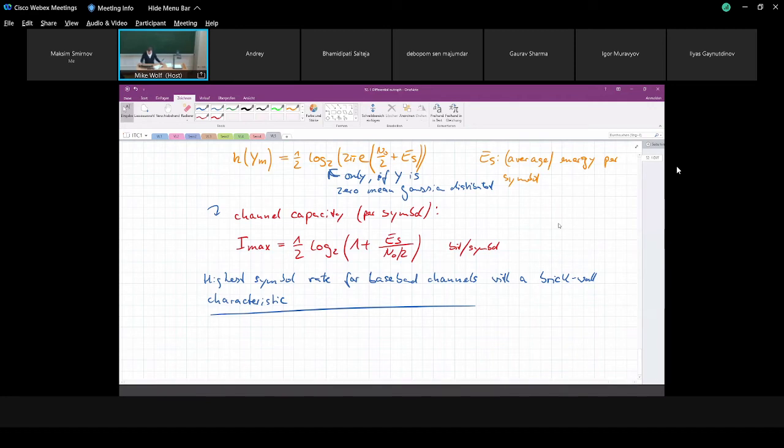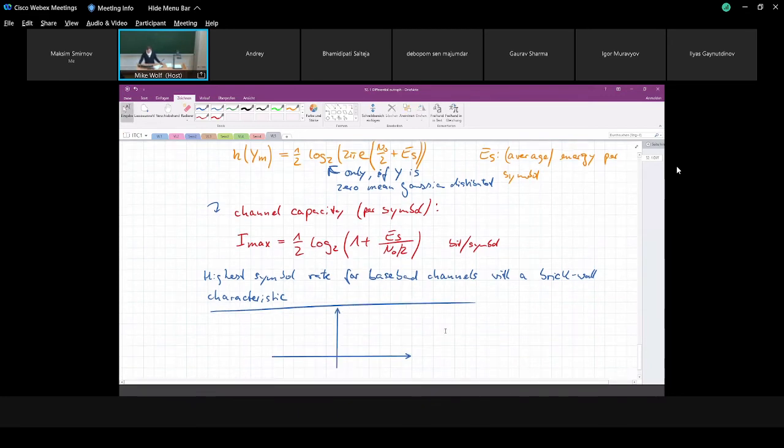Now our channel looks like this in this model, and this is exactly the question from the beginning of this lecture. Now we assume that our transmit signal needs to fit in this spectral mask, let's say. So we have a spectrum which may extend from 0 to capital B in the real world, yeah. And in our two-sided description, yeah, we use it from -b to b.